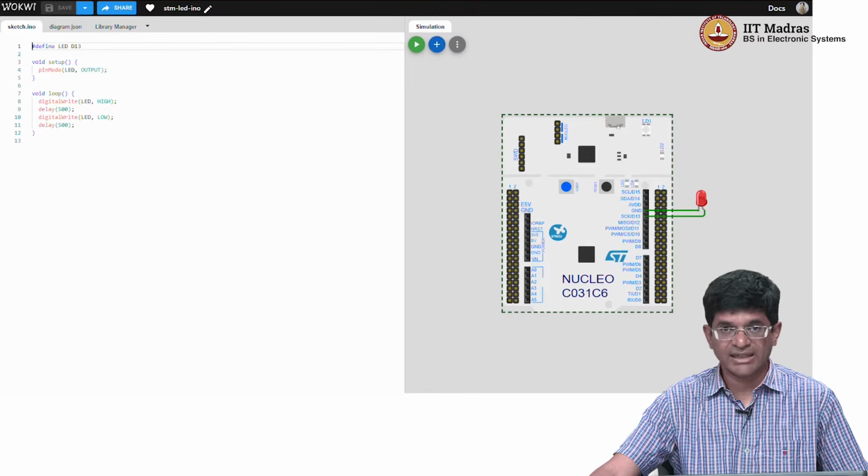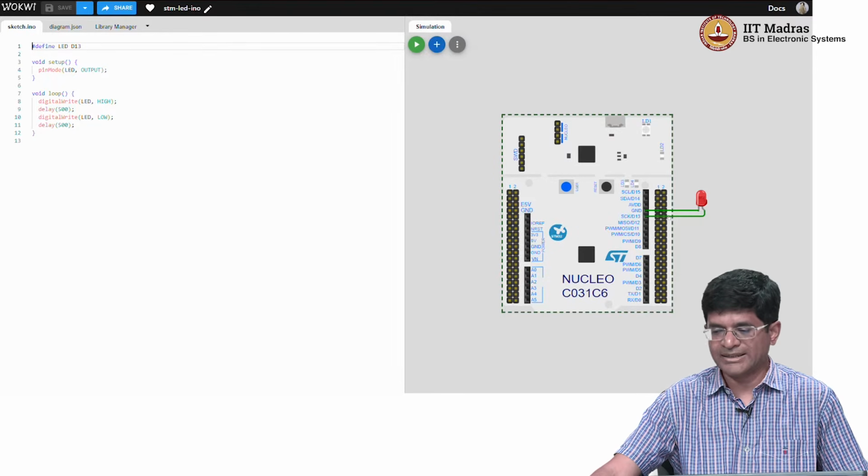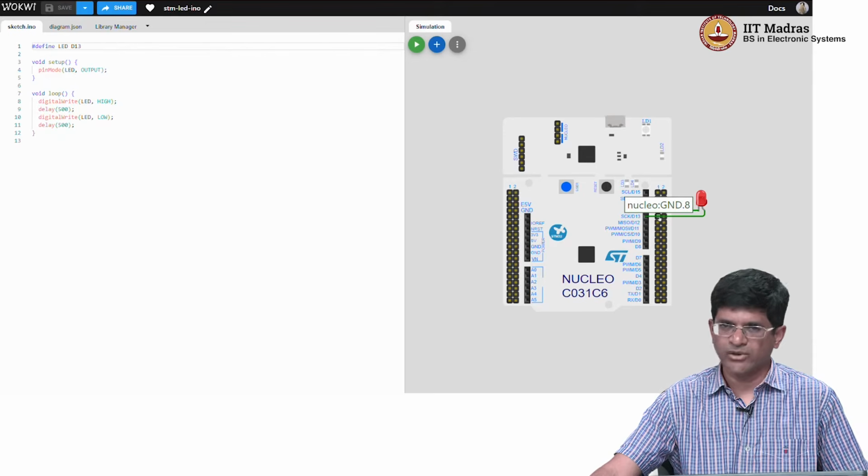The power is coming in from some other source, right? In this case, if you had the board in front of you, it would most likely be coming in from the USB connector that is used in order to actually program the board. That in turn goes through a regulator that generates a power supply that drives this. Now that's a voltage supply, but it also means that a certain amount of current is going to be drawn from that power supply. That current goes through this microcontroller and can then be used in order to also be given out through the various pins that are present over here. We will be talking more about that when we get to the section on GPIOs.